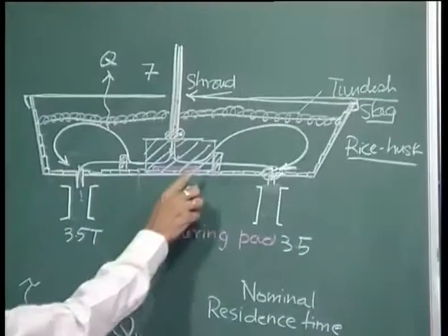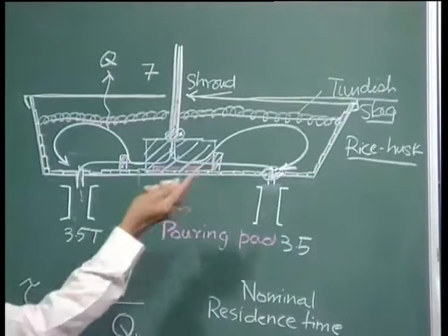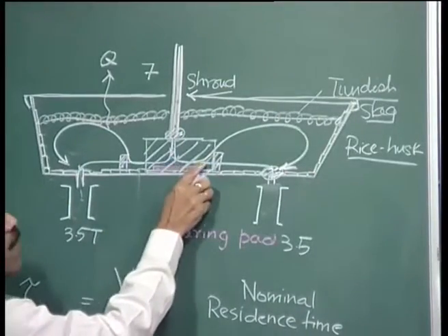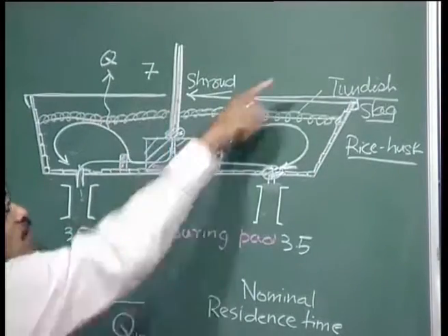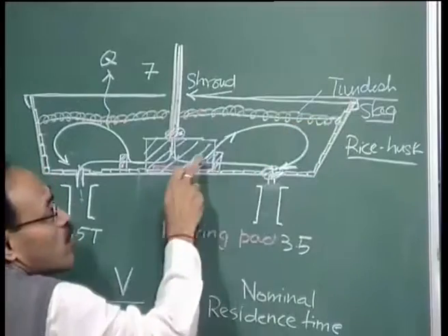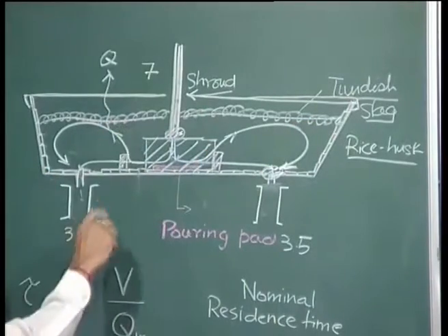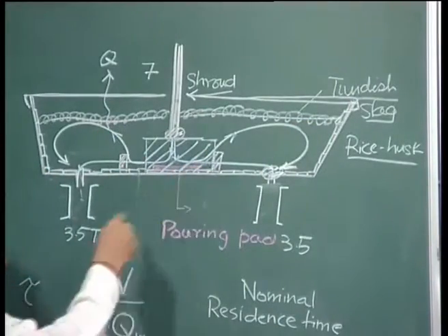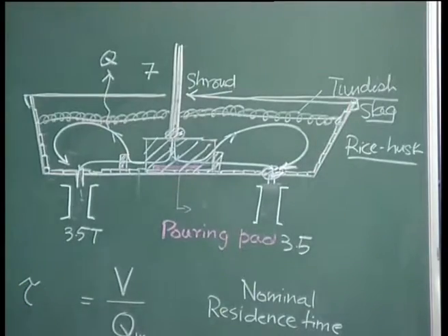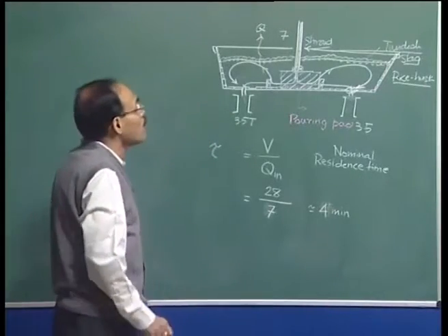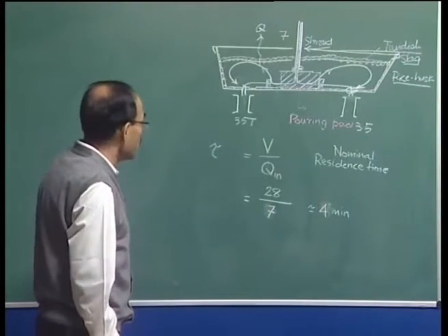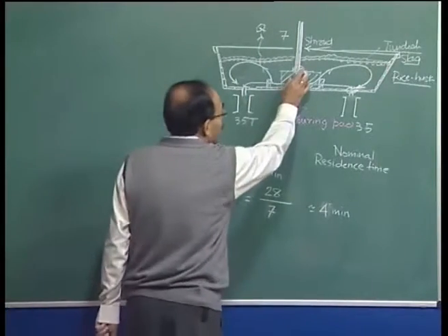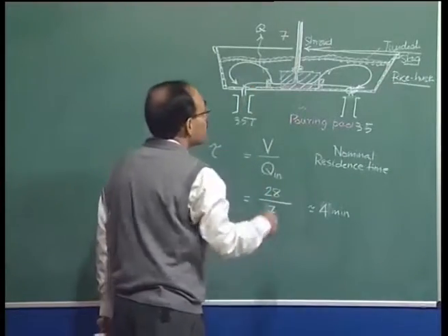So, for example, this dam would be very good in comparison to a no-dam situation, because the dam is deflecting the flow and directing it towards where? These are the slags, so it is directed towards the slag, and therefore this sort of placement of a dam is going to create a surface-directed flow, which will be very good for inclusion float out also.